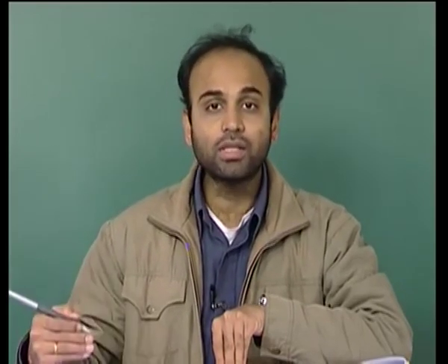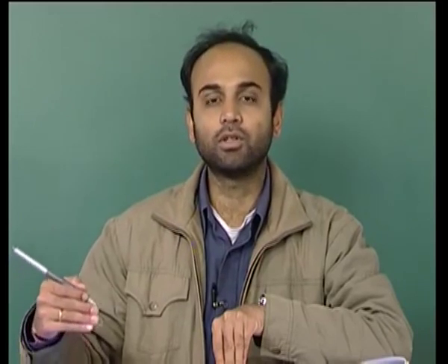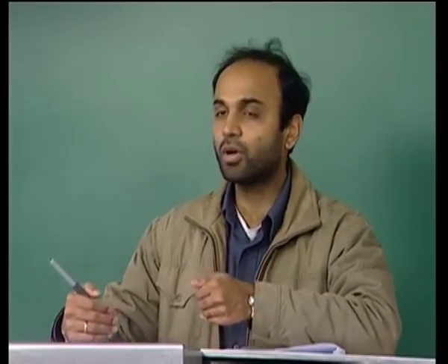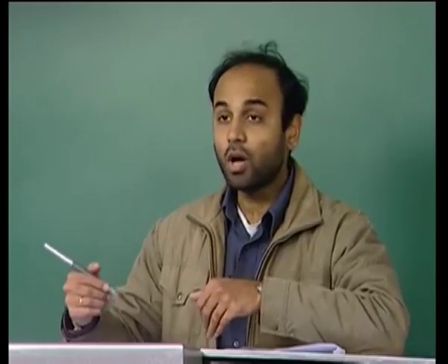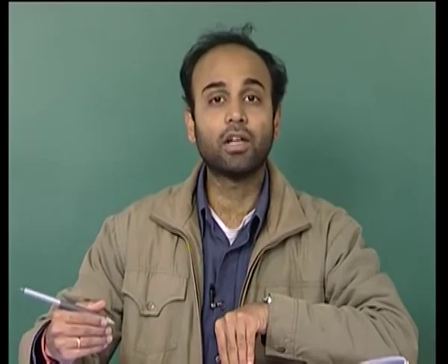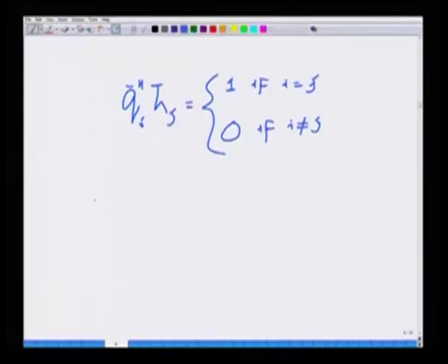Right? We knew this earlier, because Q is the left inverse of H. We had already seen this case in the case of MIMO zero forcing. However, we are now exploring this property in depth. So, now I can use this advantageously for a detection scheme. In fact, you can observe that Q1 Hermitian is orthogonal to H2, H3 up to Ht. So, I can use this to cancel the interference from X2, X3 up to Xt. So, let me illustrate this point.